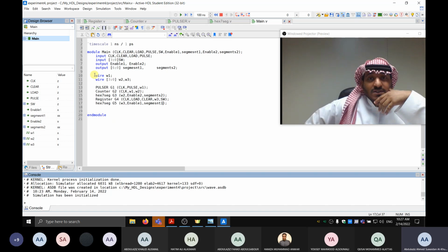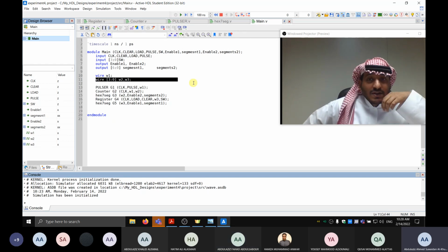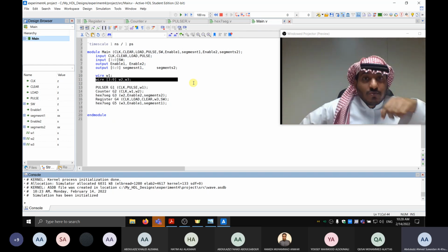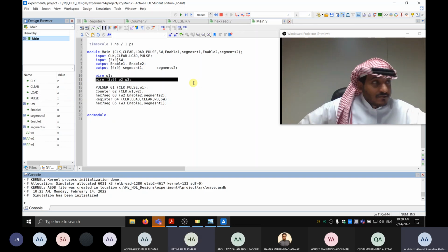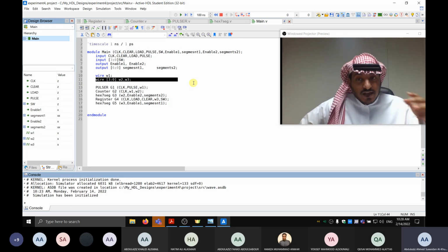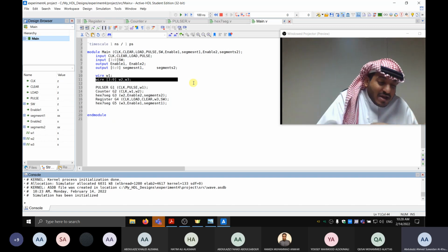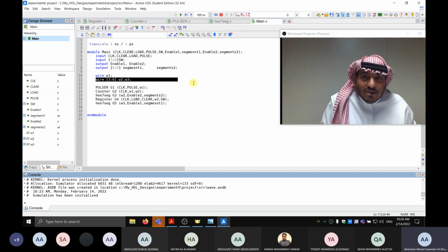Focus a little, it's very clear. If I see the output from the wires itself, that's the number we can understand, right? Yes, we can present it in hexadecimal. If I see the wires before it converts to the segments, like 0, 1, 2, 3, 4, we can understand it's working fine. There is no need to see the segments and then decode it back to see if it's supposed to be 1 or 2 or 3 or 4. So just see the wires itself.